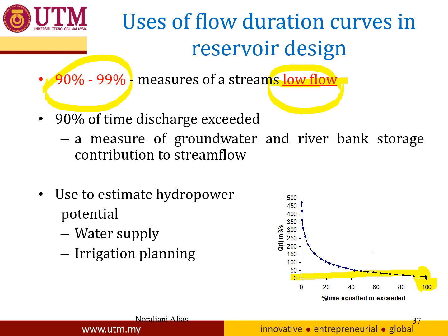This is how engineers or designers estimate the extreme cases, for example, the low flow. This is the risk exerted for the reservoir, whether the flow will be enough going inside the reservoir, and for the demand. So here, 90% of the time the discharge is exceeded.